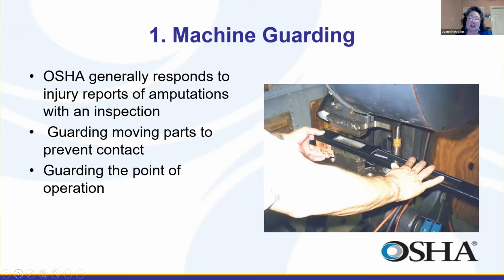Okay. And what OSHA requires for machine guarding is we require that the point of operation, which is the spot where the work is actually done, is guarded. So in the picture, you can see that that's a power press, a mechanical power press. And in the middle, between the two guys' hands, you can see there's a ram, and the ram goes up and down. And what it does is it goes chunk and it chops out that piece of metal, which is already missing on that particular piece of metal that they're pressing, punching out.